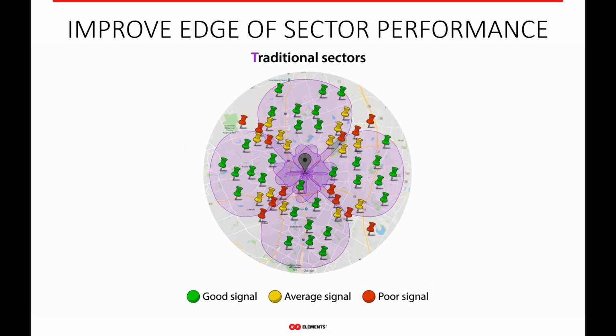If you've ever looked at your radio and wondered why chain 0 sees a negative 50, right? And chain 1 sees a negative 55. We've seen deltas much higher than that, but as an example, that 4, 5, or maybe 6 dB of difference in intensity between chain 0 and chain 1 really reduces your MCS rate. You really require both chain 0 and chain 1 to have no more than 1 to 2 dB of intensity delta in order to maintain the higher MCS rates and stay at a stable MCS rate, which is even more important.